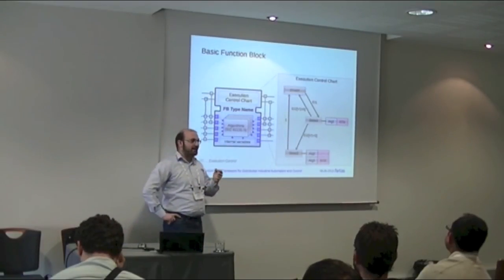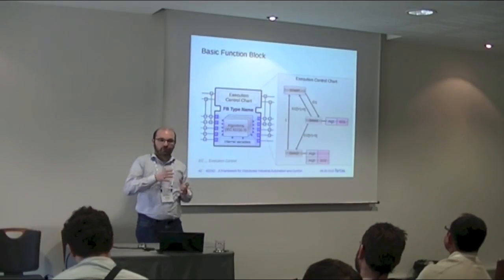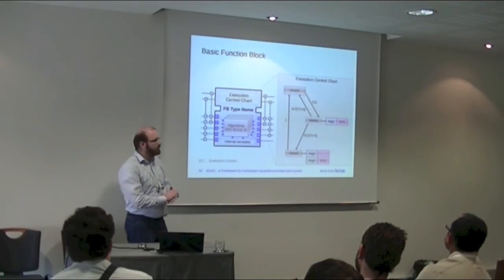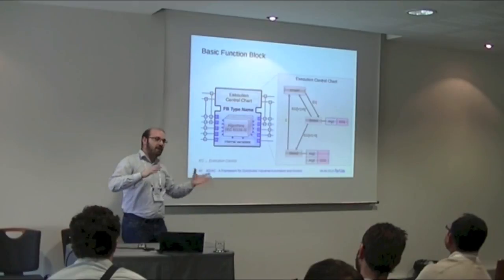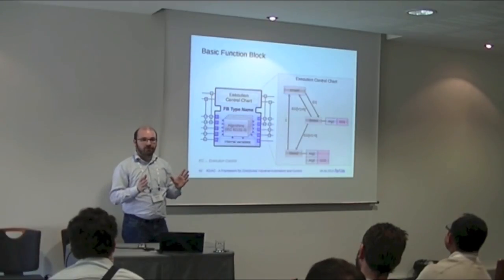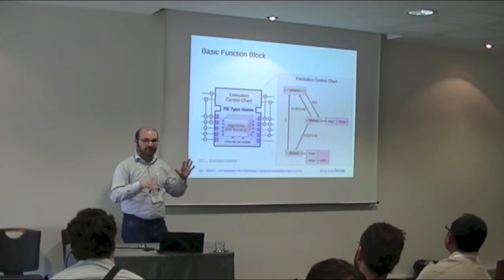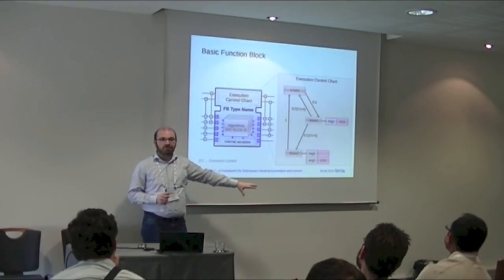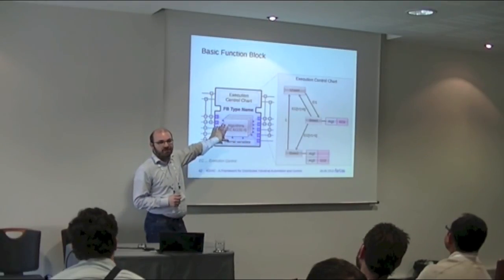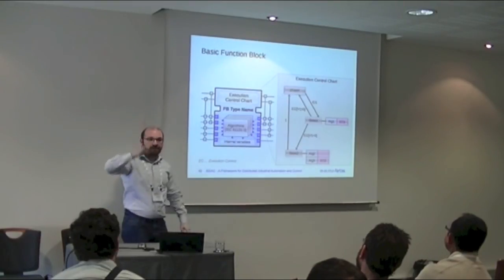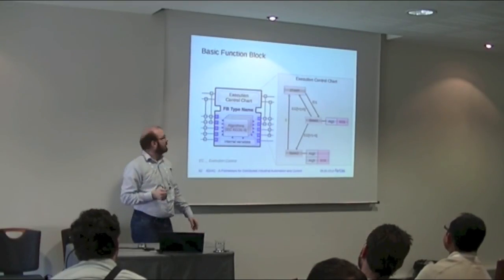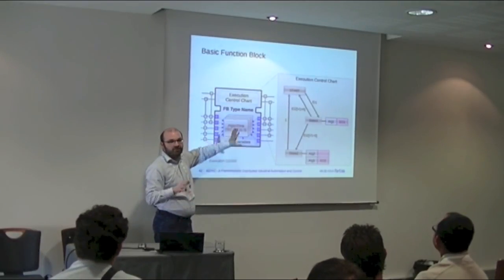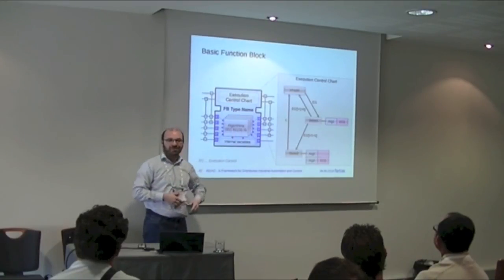On the other side, in order to make the tool a little bit more manageable, we are currently encouraging you to use 61131-3 structured text, which is a Pascal, Modula-2, Ada-like language. So you have whiles, for loops, if-then-else, switch cases and stuff like this. And this we all bunch together, and from this we make C++ code. This makes our code generation rather easy, because the interface is just some data files, some arrays with parameters, and the hard part is only the algorithms. So therefore I'm pretty confident in our C++ generation.